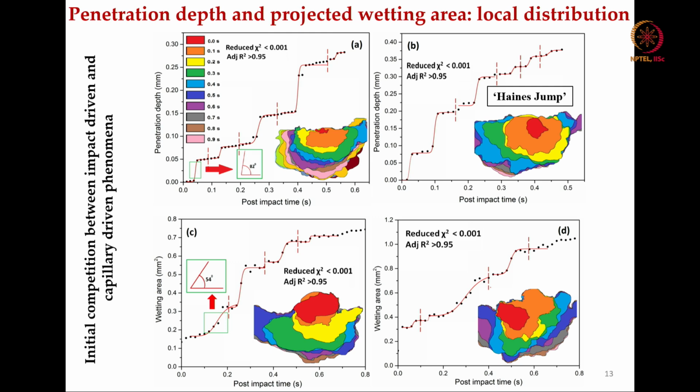So when this binder droplet penetrates or interacts, this is more impact driven at the initial stage. But then when it goes into this print bed, there is a transition from impact driven to capillary driven phenomena that actually drives this wetting of the powder bed with the binder.